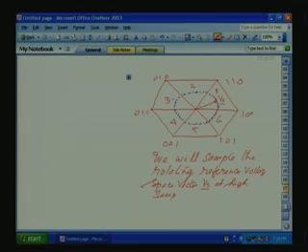This sampling frequency we can relate to our sine triangle, equivalent to the carrier frequency, the triangle frequency, where the frequency of the sine is proportional to our continuously rotating reference space vector, and the sampling period is proportional to our triangle period. We can relate that. So, when you sample it, till the next sampling period, we will assume Vs is stationary.